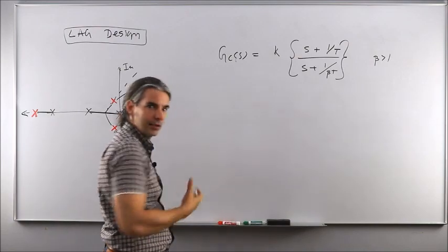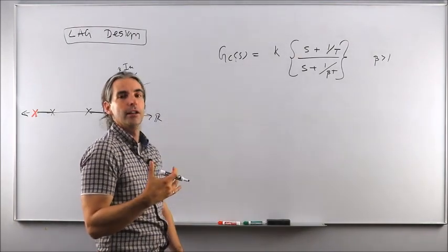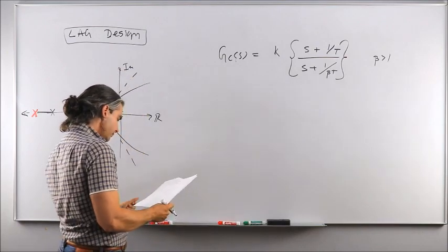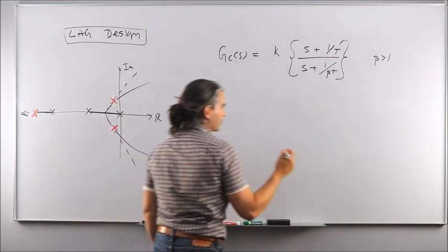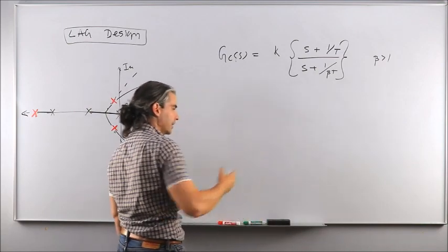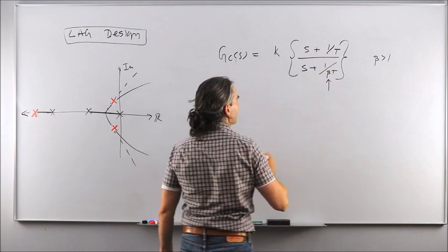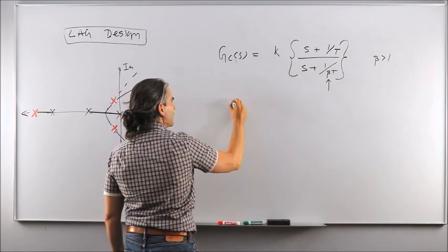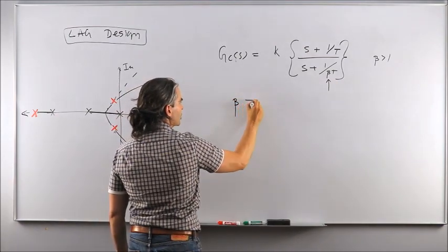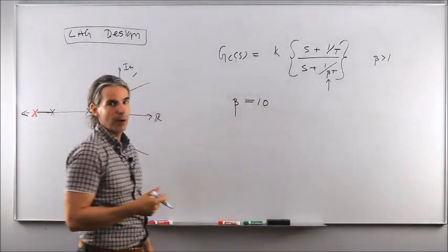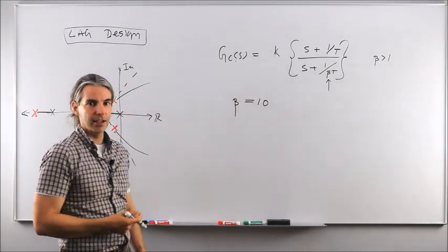This is the opposite situation than we had with the phase lead compensator. Okay? Turns out the factor by which you need to increase your Kv relates to beta. Okay? So I'm going to say that beta that we need shall be equal to 10, because this is the factor by which we need to improve the steady state performance.